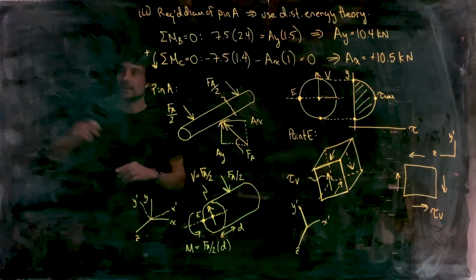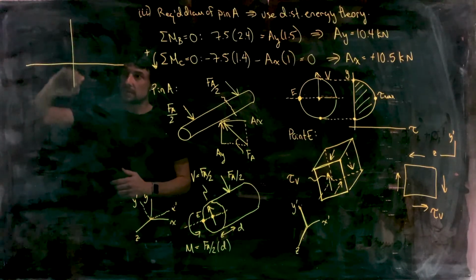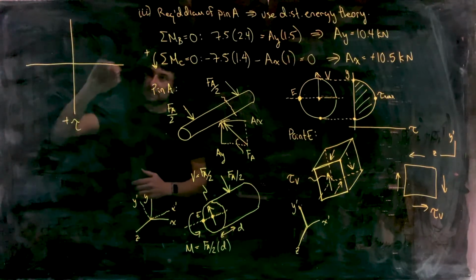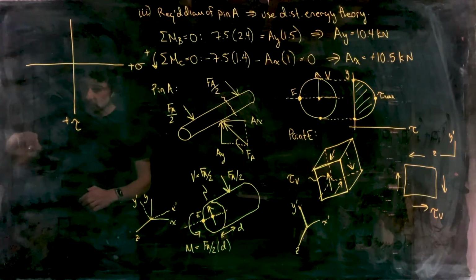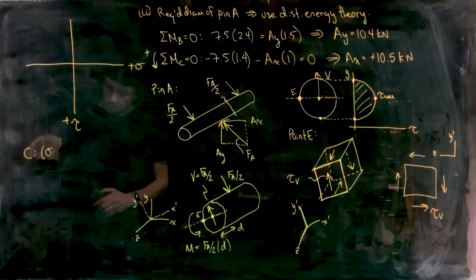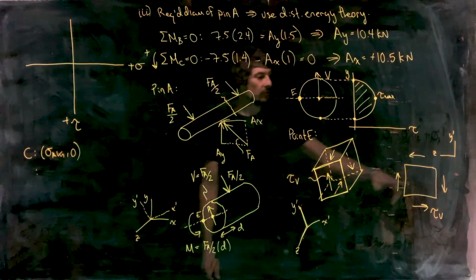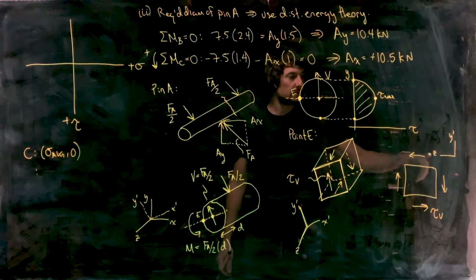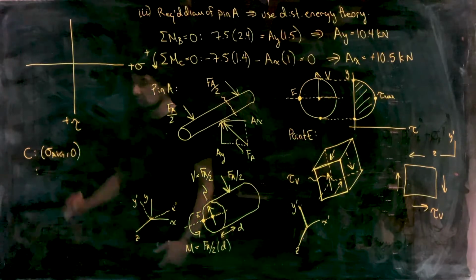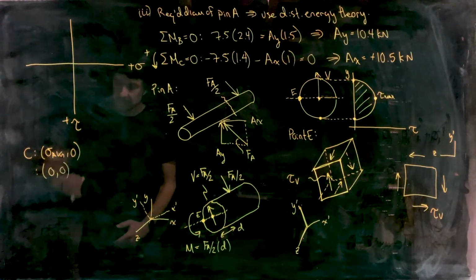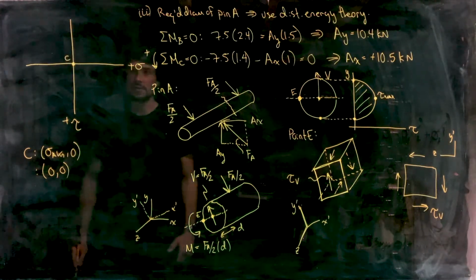So let's set up the axes for our circle here. So we've got positive shear stress, positive normal stress. To plot the circle, we need point C, the average normal stress on our element, comma 0. The average normal stress here is 1/2 of sigma z plus sigma y prime. That's 0, right? Because there's no normal stress. So the center of the circle is 0, comma 0. So the center is right at the origin.